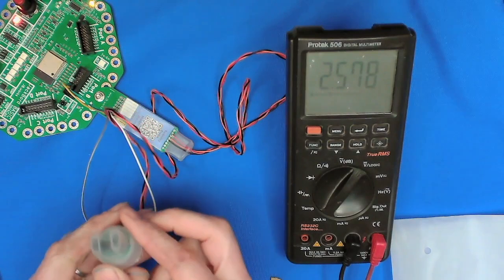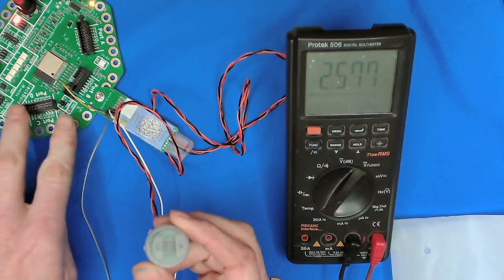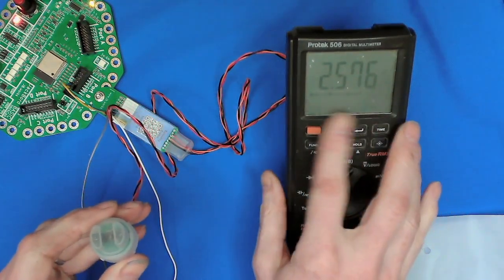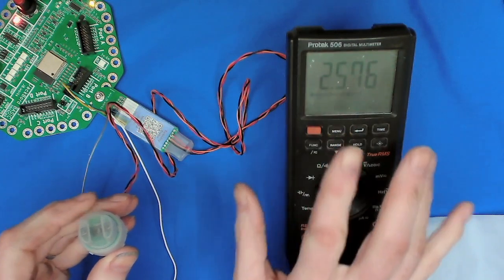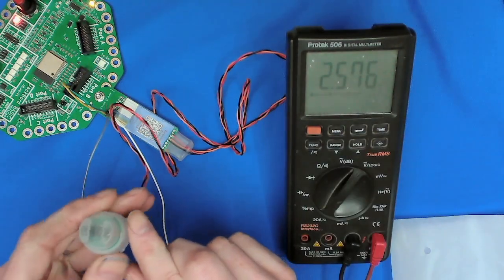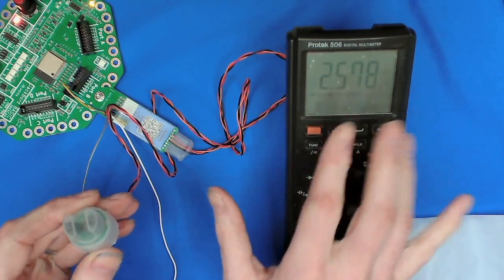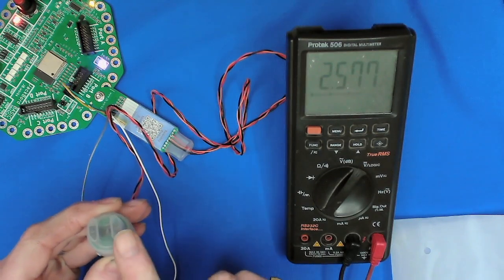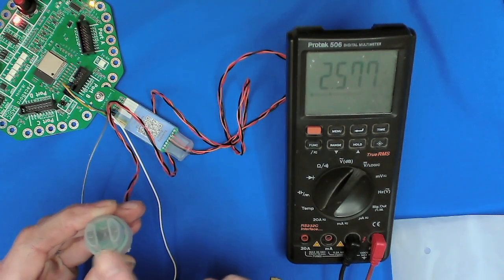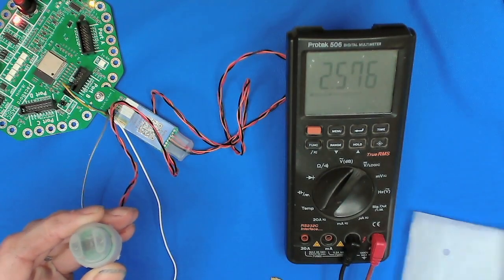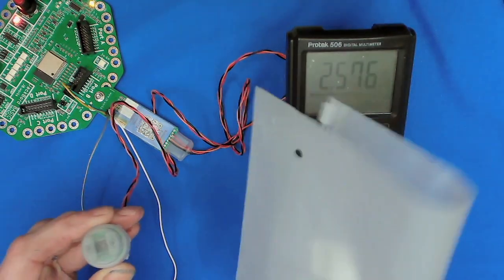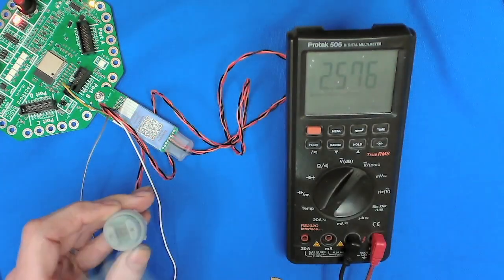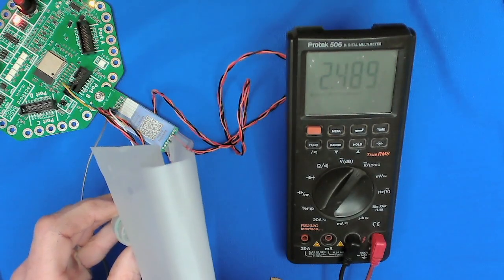Okay, I've got a turbidity sensor here, and it's connected to the JackBord Basic just to get power, so it's only getting power. And then I'm using a digital multimeter over here to measure the voltage that's coming out of the turbidity sensor. And so right now you can see it's about 2.57 volts, and that's because there's no material between the sensors, which are these two here, and effectively the turbidity is 0, so it's very, very clear. And then if I was to take something like this bag, and if I was to put it in, you can see the value goes down to about 2.4 volts.